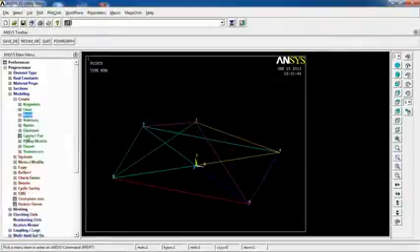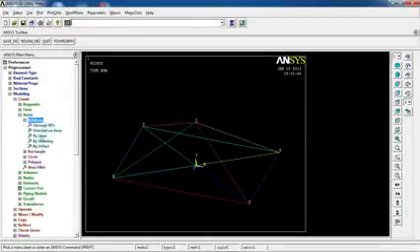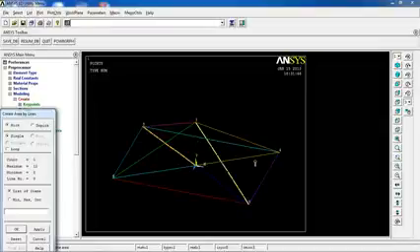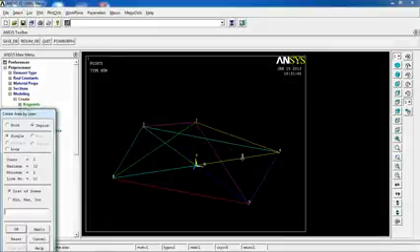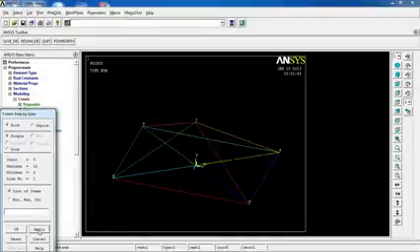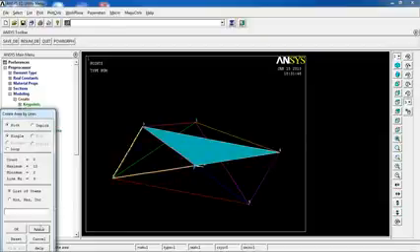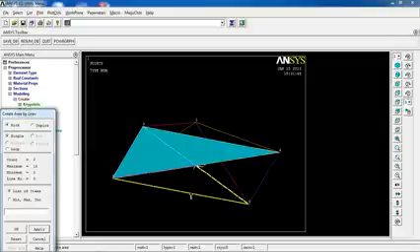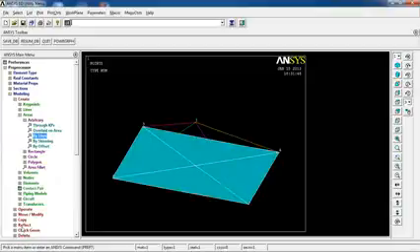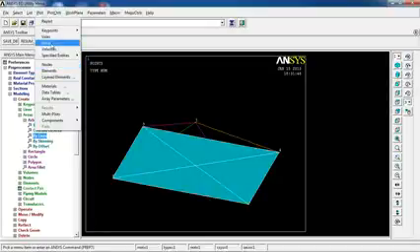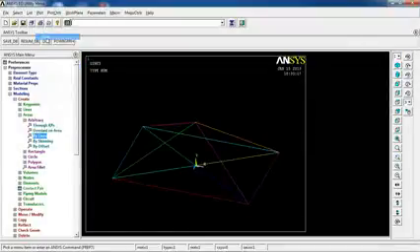The next step is I'm going to make some areas arbitrary by lines. So I'm making this, oops, nope. It's getting hard. Okay. Pick that one, pick these 3 lines and make an area. Pick these 3 in another area, and finally the final area. But let's plot only the lines because I want to use line sizes to do the meshing, so I'm only plotting the lines.